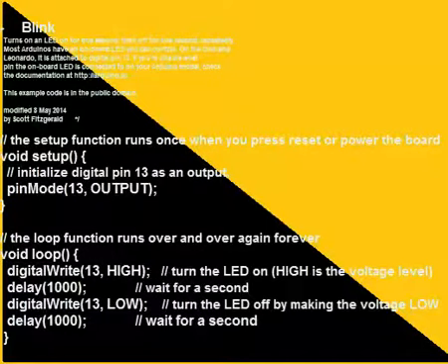In the Arduino IDE, you will find example code for blink in File, Examples, Basics, and Blink. Within that code, you'll see a comment block, a variable block, and function blocks. The comment blocks are notated by a /*, and you will put multiple comments in there.